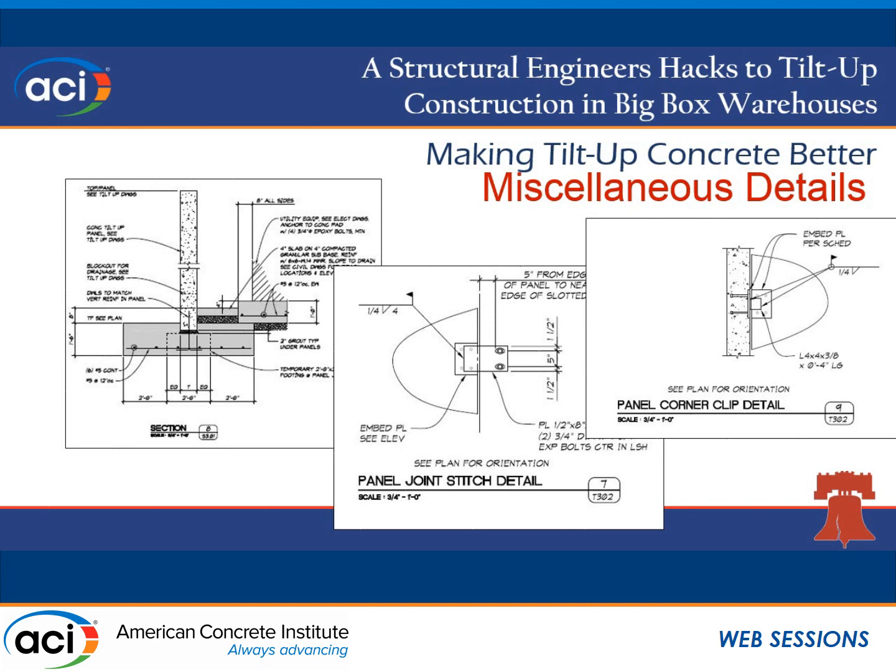Do you see that if they're pinned together at that location, since we've got shrinkage issues on like the outer third of each panel, do you ever develop cracking around that? I haven't seen too much cracking from that. Okay. I see many more of, and again, this is probably an excessive amount of weld, even though it's nominal. Really, you really just kind of want an inch or two of welding. But most of your cracking is going to come from the welding process and